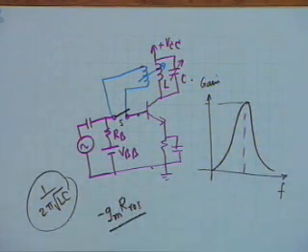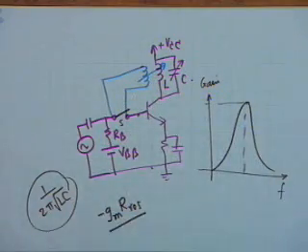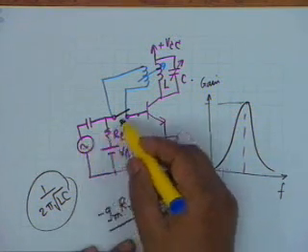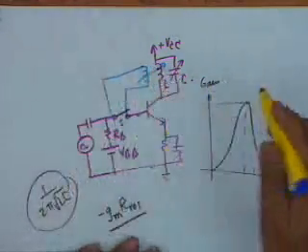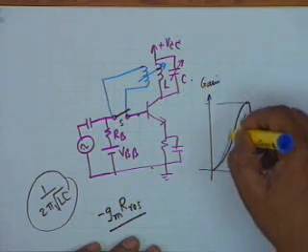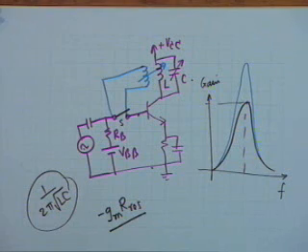And this is a very practical circuit. You feed back a part of the output, and if the feedback signal helps the input signal, that is, if these two, Vi and the feedback signal, are in phase, if they help each other in the same direction, then you will get an enhanced gain, all right. The gain shall increase.